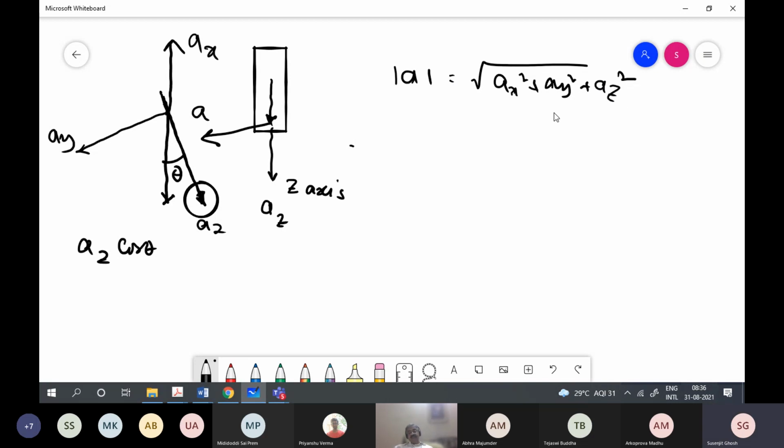So then the cross-axis sensitivity will now come into play. But since in the problem, what is given is that the actual acceleration is happening along the marked axis and the sensor package is misaligned, we are only using this measurement.